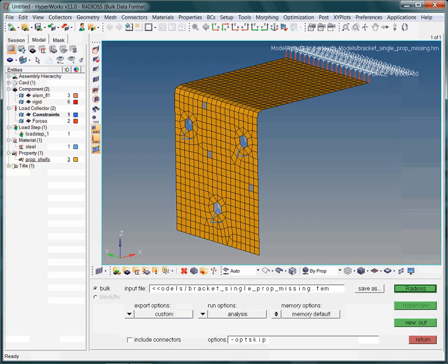Note the gray-colored elements. The gray color typically refers to elements without property definition. Based on this understanding, the next steps are rather straightforward. We need to assign a property to these elements. Of course, other options for checking and displaying elements according to their property do exist.